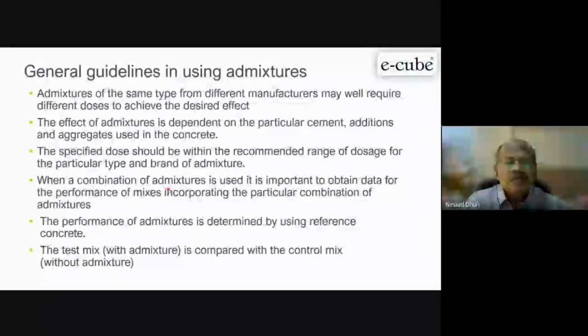Now, sometimes you are using a combination of admixtures also. That is also important. Suppose I use only super plasticizer and my long haulage is there, 3 to 4 hours. Suppose I have to supply concrete from Mumbai to Pune and transit I require 4 hours. Concrete should not set.